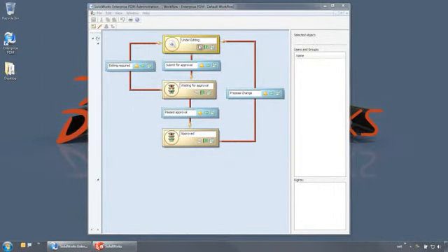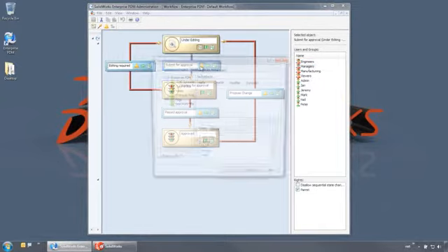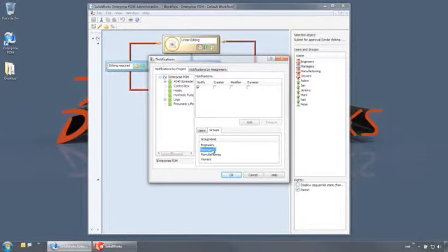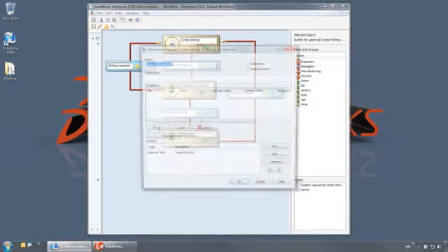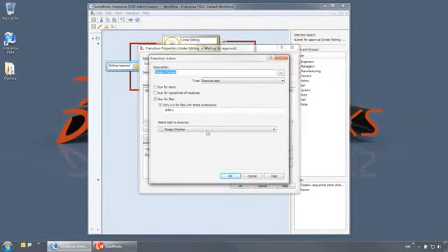The gold boxes represent workflow states, and the blue boxes represent transitions. Each state and transition can have their own permissions, notifications, and actions that can be performed. For this workflow, all new documents start out in the under editing state, and when complete, they are submitted for approval. Only users in the engineers and managers groups have permissions to use this transition. This transition automatically sends a notification to the manager's group, and a task is automatically triggered to perform a SolidWorks design check before it moves on to the waiting for approval state.